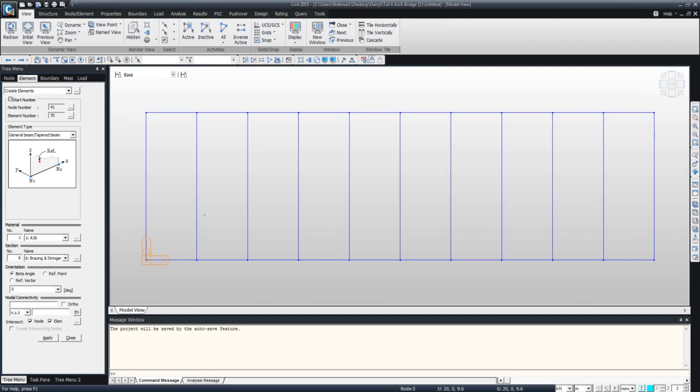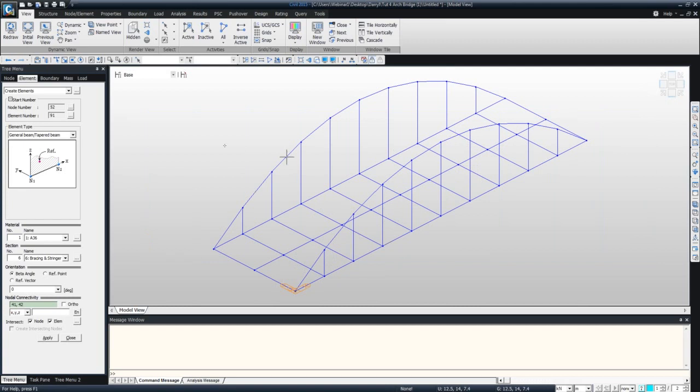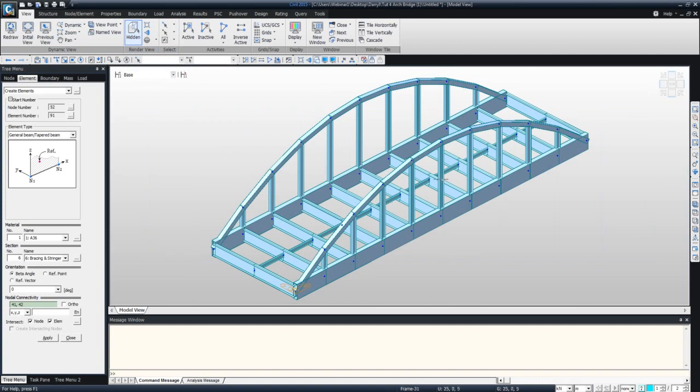Okay. So going back to the model here. If I go here, as you can see, it automatically goes to the center of the elements, and I can change this to 2/3, 3/4, etc., and it'll cut it into 4ths or thirds. So just make sure that this setting is set to 1/2 so you can divide appropriately. At this point, all you need to do is go right down the center to create your stringer going down there. So we'll go straight across. And then, as you can see, now I have my stringer going through the center. It's always a good rule of thumb to double check that you have the right element created. Okay, so that looks good.